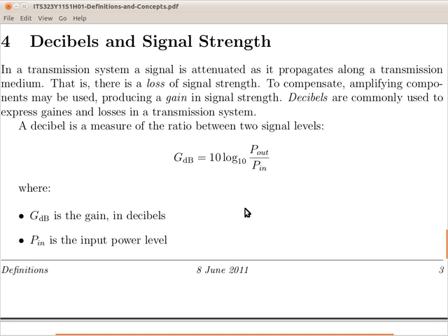And we can apply the same equation to convert to decibels. To convert the ratio to decibels, simply take the logarithm in base 10, multiply by 10. Log of this is 3, multiplied by 10. Our loss in dB is 30 dB. To convert between the decibel values, the gain is the negative of the loss, and vice versa. Minus 30 dB gain is 30 dB loss. And that's why sometimes it's easier to work in decibels.